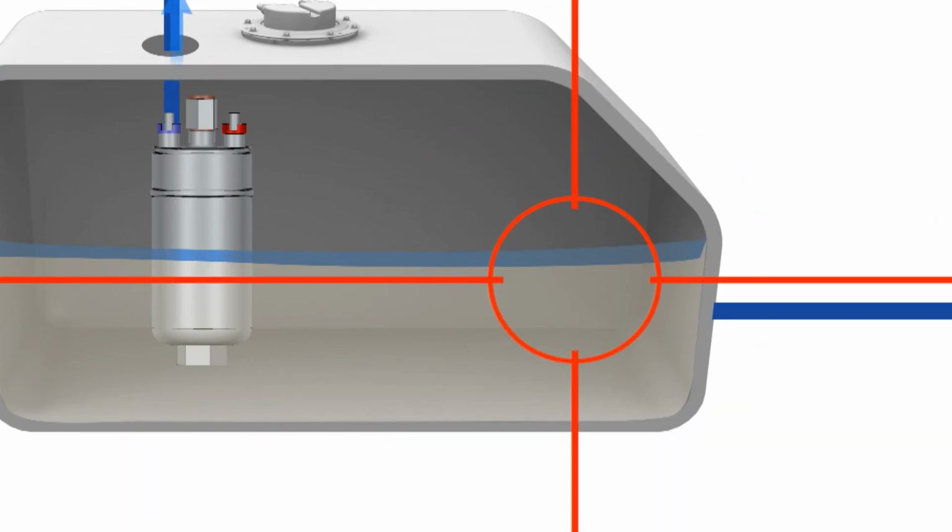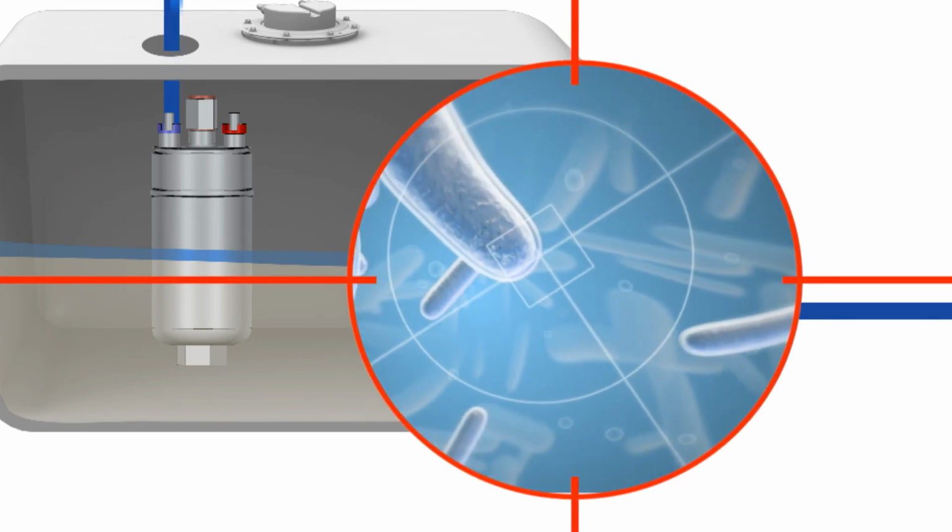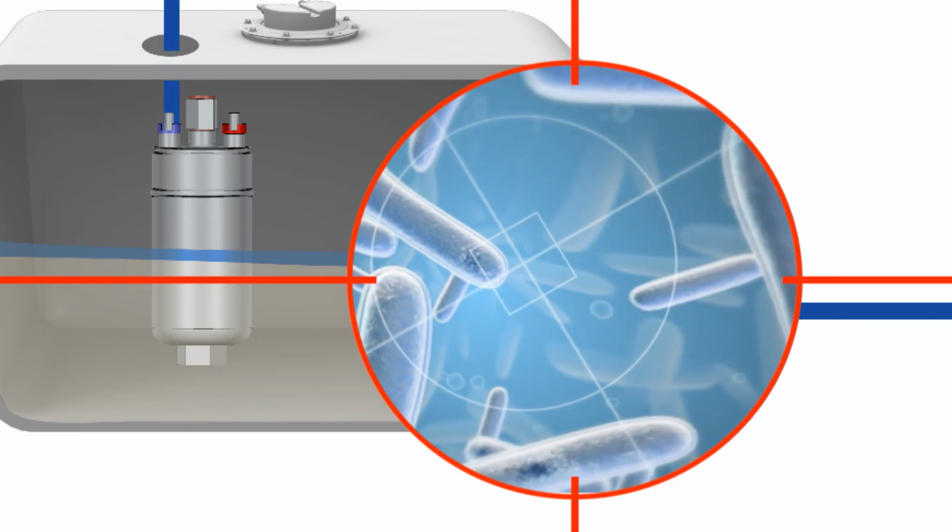Water in the fuel can cause corrosion. Many parts of the high pressure pump and injectors have extremely fine clearances. Any corrosion here could be disastrous. Bacteria and fungus can live in the water, feeding on the hydrocarbons of the fuel. Clean, good quality fuel is essential for common rail diesel engines.